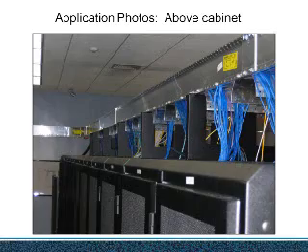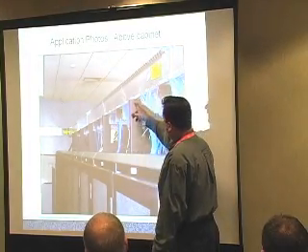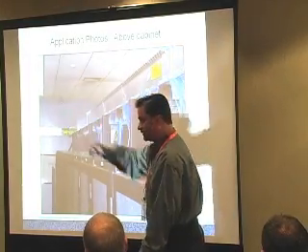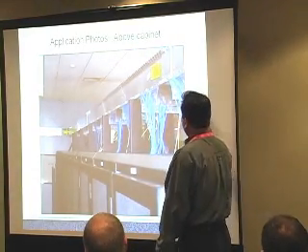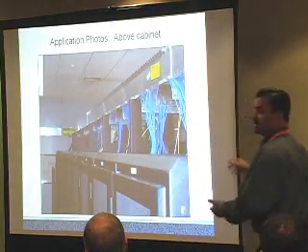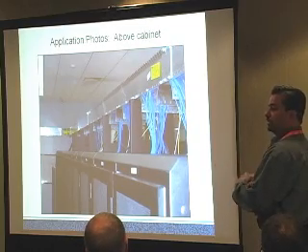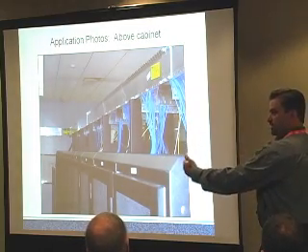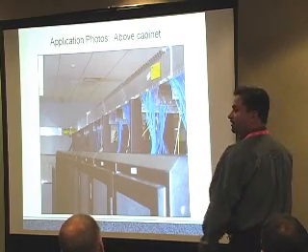And many different variations of it. You saw a ladder rack here. This is an aluminum tray. This customer wanted a specific height for where else he was going in the room, so we made custom ladder rack brackets for him, and they have the waterfalls. And all the cabinets have various cable access points in the top panel. On a 24-inch wide, it comes through the center of the top panel. On a 30-inch wide, you're able to bring it to the sides and stay outside the air intake pattern, and that way it keeps it much cleaner for airflow.